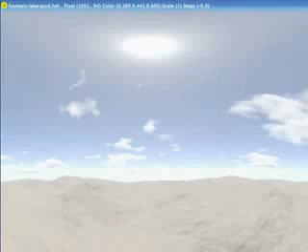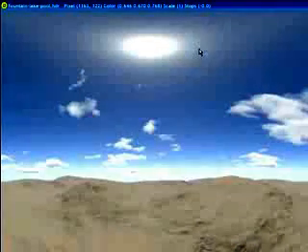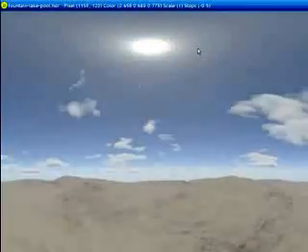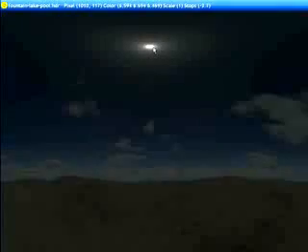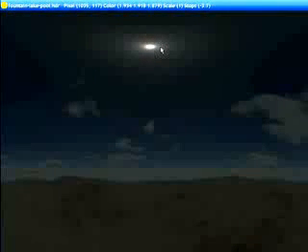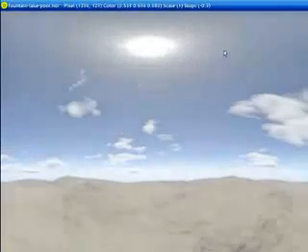In Module 3, I introduced the concept of luminosity and how taking a picture of midday sun results in a clipping of the pixels that want to be displayed at a higher range than the maximum 255 allowed by most image types. Well, the HDRI file type allows for an additional channel of information, which is luminosity or radiance. The end result of this type of image is that it appears to look like any other image with common viewing programs, but it really contains the added luminosity information that can be used to create illumination in a scene.